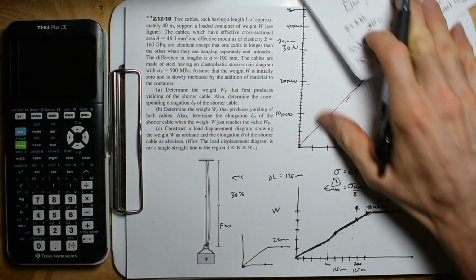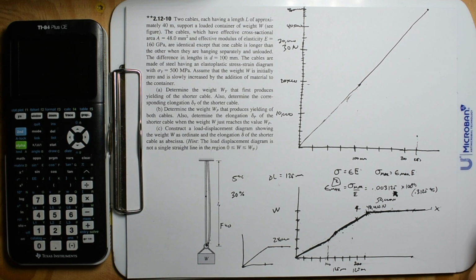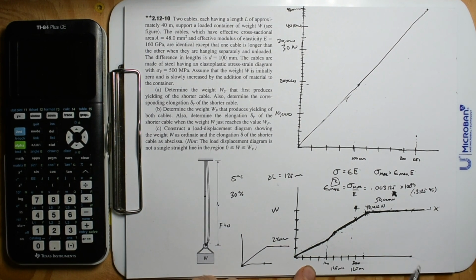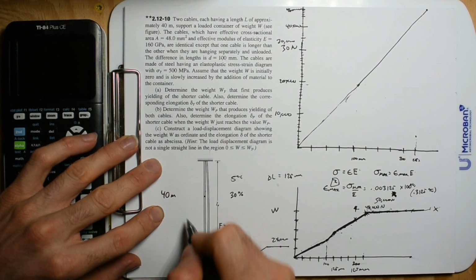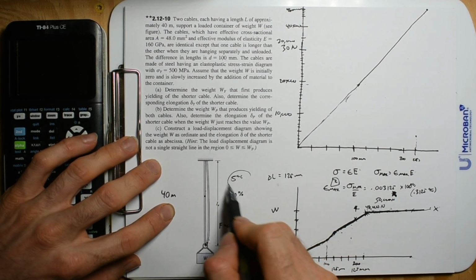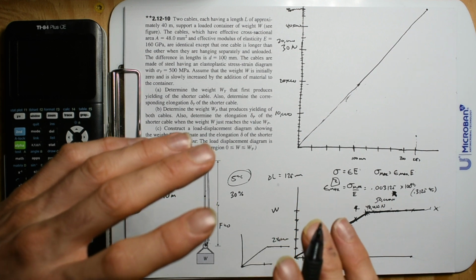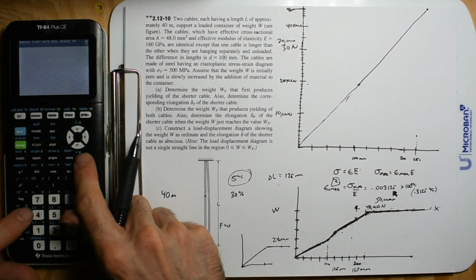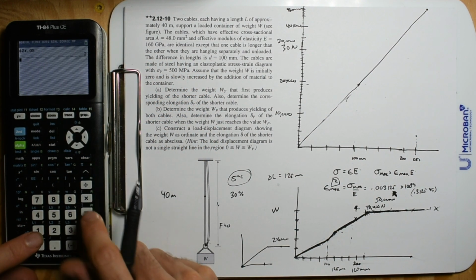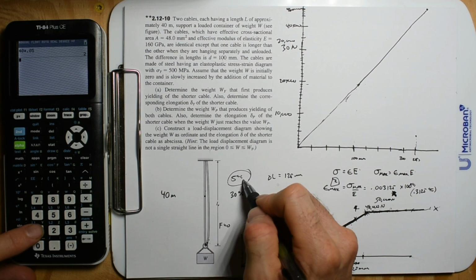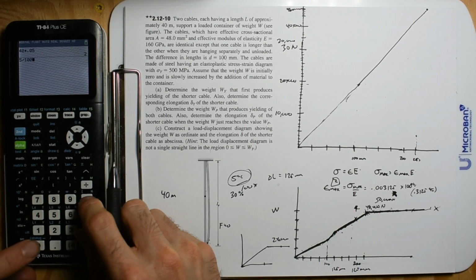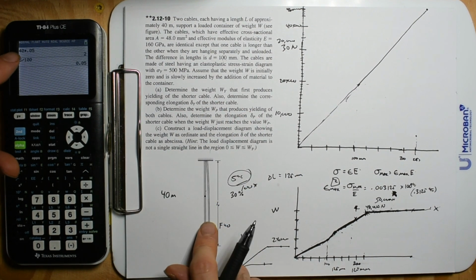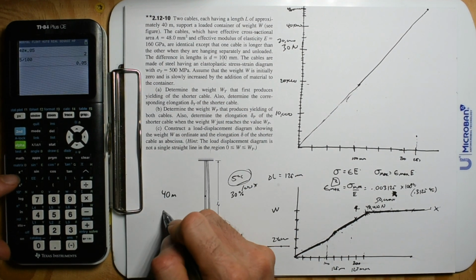Okay, but the take-home message is going to be pretty cool on this one. It's going to show you that 125 millimeters is potatoes compared to... So if you have something that's 40 meters, and I say it can stretch a max of 5% before crap hits the fan, we're going to go 40 times 0.05. That's how you do 5%, because 5 divided by 100 is the ratio, 0.05. That's what we multiply by 40, and you get 2 meters.